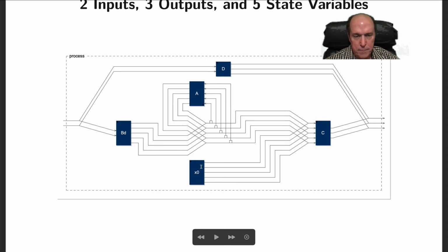So the state initial condition comes in here, and it fires at time 0. Remember, it's got those impulses multiplying it, so it only fires at time 0 and goes into the C matrix at time 0. And then this delayed B matrix holds off the input for time 0 because it should not affect the output at time 0. Anything that affects the output at time 0 from the input goes this way. The D matrix takes care of any direct bypassing of the state dynamics part.